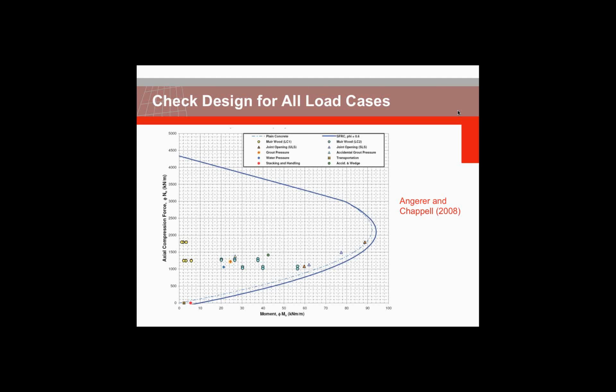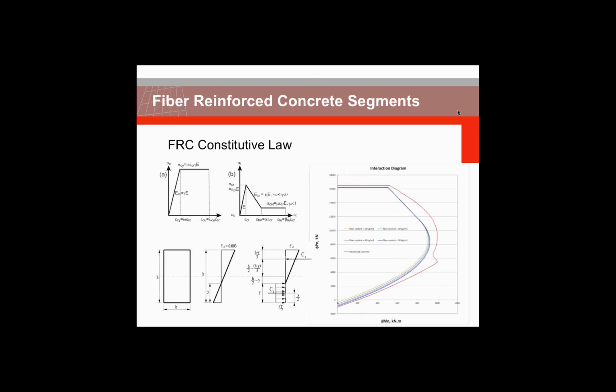But as you can see in this figure, the strength of the plain concrete segment is not really sufficient for the studied load cases, especially for the load case of stacking and handling, and then also for the load case of transportation. But you can see that a fiber reinforced segment can take these internal forces.